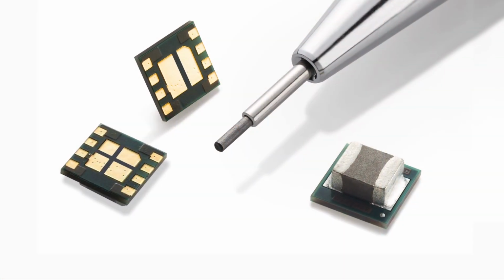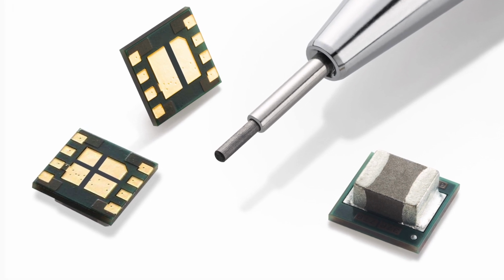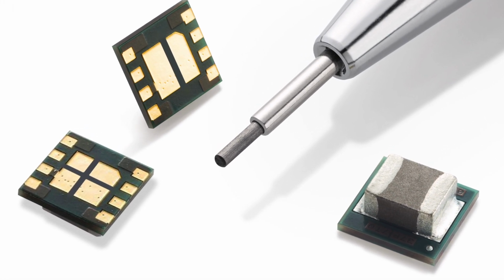As system designers, when you're looking for a power management solution for relatively low power rails, you'll often have a choice between a switching regulator or a low dropout linear regulator, also known as an LDO. Today we'll examine both solution types and weigh the pros and cons of each in a few common scenarios you might face. But in each comparison, the switching regulators we'll use will be from TI's family of easy-to-use simple switcher nano modules, which are synchronous switchers with integrated inductors in a tiny solution size.